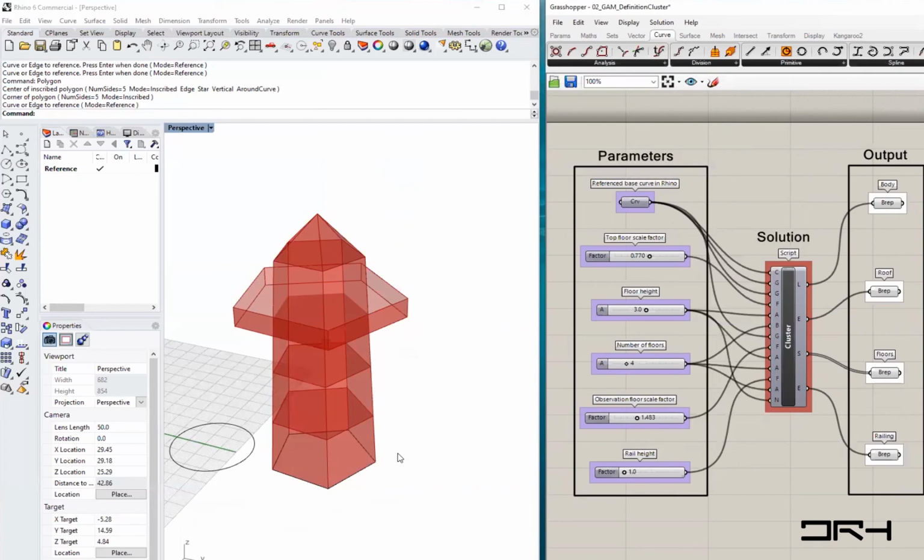So this is the minimum and maximum curvature value. The curvature is the rate of change in direction along the surface, if you will. If you have a circle or a line, your curvature is not changing, it's constant, because along a line you're going in the same direction all the time. With a circle over 1 unit length, the change in direction is also constant, although you're turning.